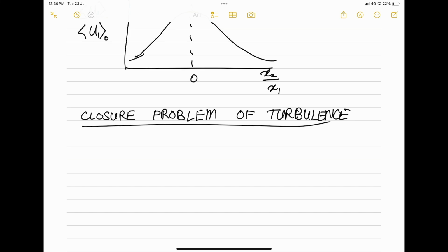What do you understand by this, if you have heard it? So, there are some models like the K-epsilon model. So there is a closure problem. No, but what exactly do you think the closure problem is? Means equations... Yeah, right. Equations are fewer and the number of unknowns is more. Closure problem in any physical problem is when you have fewer equations and more variables.